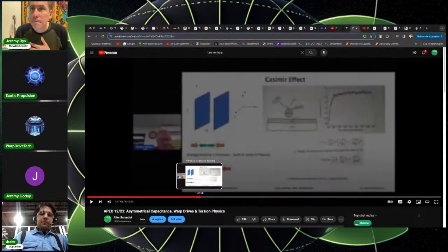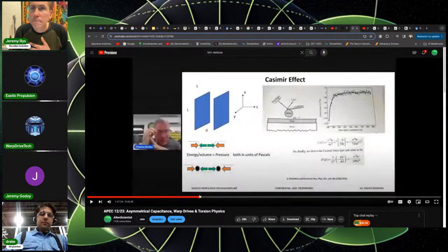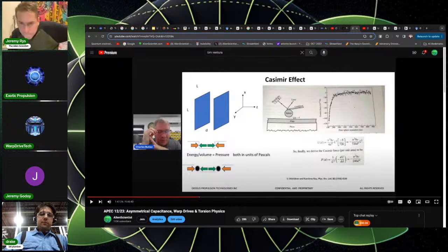You cast it, not so much machine it. You can clean up the surface, but generally speaking, you need some of the more difficult to acquire, high temperature, cured, and sintered dielectrics, for example, barium titanate. A very good solution for this because barium titanate will generate an incredibly strong evanescent wave, and it happens to have a material property called, what is it, ferroelectricity.